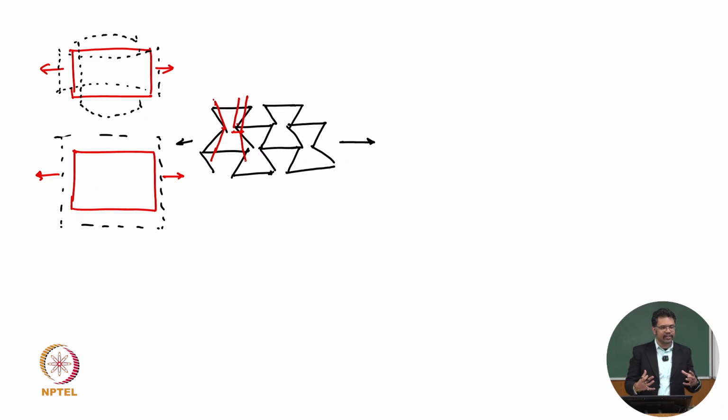So you can see that the volume or the area is actually getting extended on both sides. Now if you think that, okay, whether the bulk modulus is getting increased, no, you should not think of it that way, because there is a void internally, there is no material. Whichever way you look at it, it gets expanded in that way. So now if you see the overall Poisson ratio of that material, it is expanded, or that Poisson ratio becomes a negative Poisson ratio.